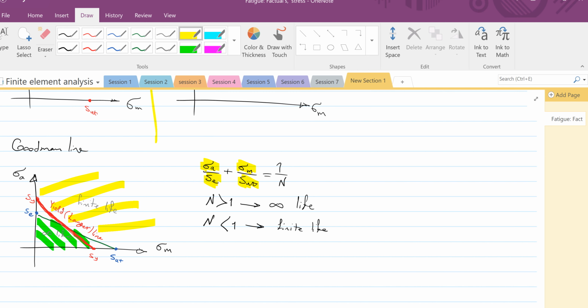And the good thing is ANSYS can do this fatigue calculation for all those mesh points because they have different maximum and minimum stresses in those areas, and you can find the local area of your design with lower cycle of life, which you need to redesign or increase or decrease the load to make it above 10 to the power 6, or 1 million life, to be able to claim you have a design with infinite life.